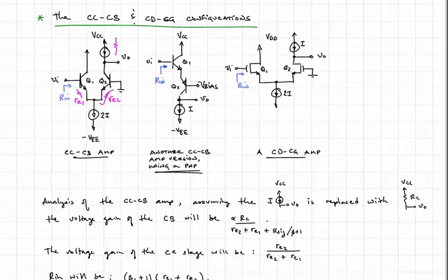When this is designed, typically Q1 and Q2 are matched. So imagine that at VI equal to 0 volts, the base of Q1 and the base of Q2 are at the same voltage. Their emitters are tied together, and now you're pulling 2I from both of them together. There's a symmetry, and so current will split between the two, and each transistor will carry half of 2I. So each transistor will be biased at a current of I.